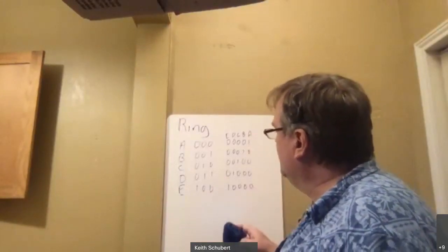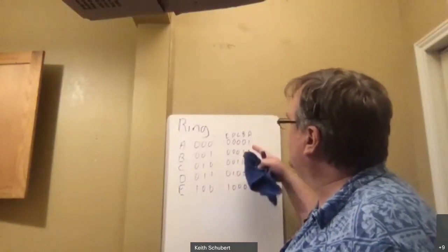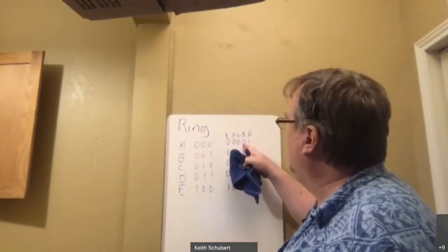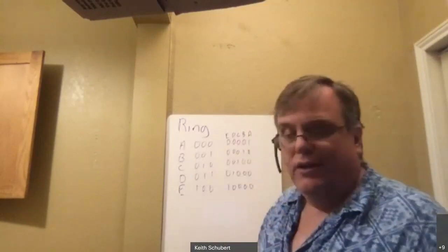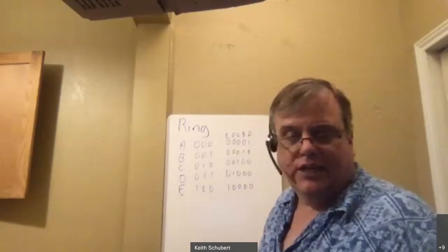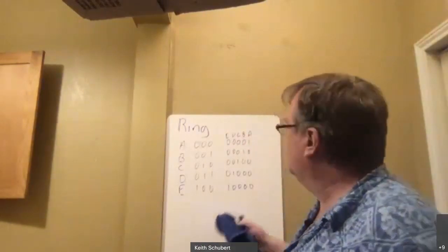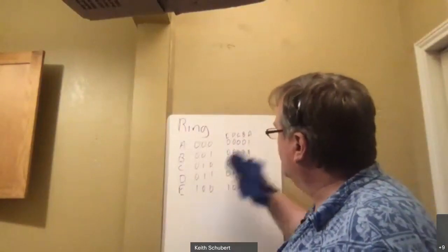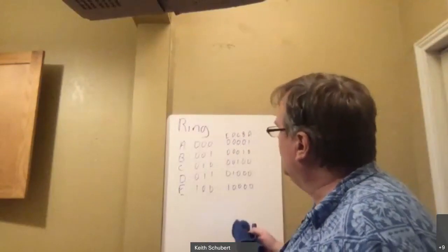One hot is a little bit easier to handle because I only have one on. So if I'm doing a transition, I can turn B on and then turn A off. And I know that in between, when they're both on, that's not a legal state to be in. So I know that's part of a transition, so I can reject the errors on it and continue through. I'll only use it when only one is on.